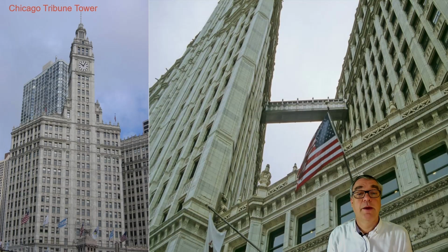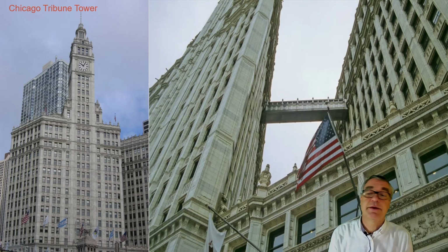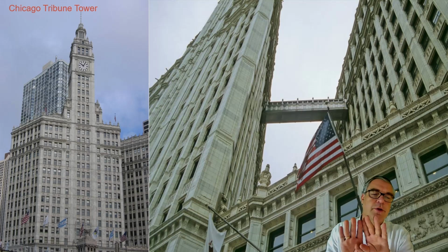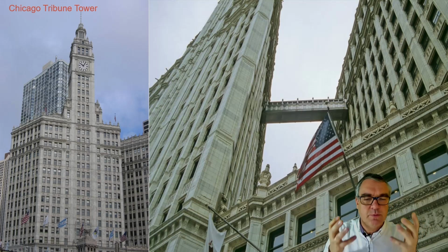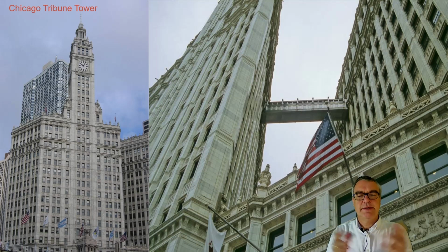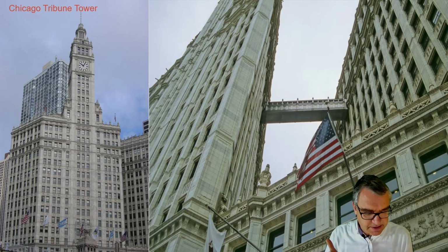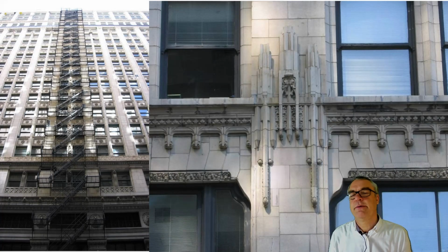One of the very rare buildings, versus these buildings where we see they have the same dimension at the top part as well as at the bottom part in the outer cladding. And here I call it cladding because we know there's a steel structure behind, and that steel structure is then wrapped with a natural stone or artificial stone or brick to clad. It aesthetically delivers some similarity to the pure brick and dead load oriented buildings, but we now understand by the dimension of the windows that this needs to be a skeleton structure which is behind.